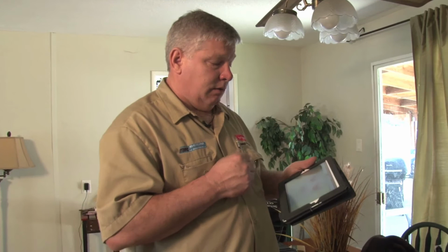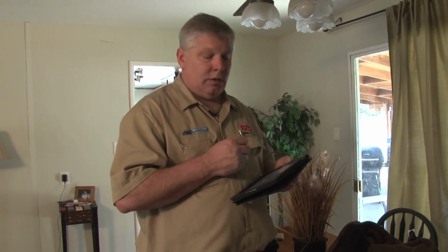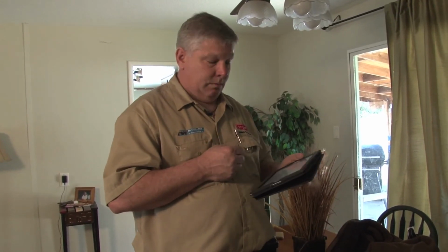And with that, we're going to say a 3.5 ton cooling system is required. The heating is not going to be a problem. We have a package unit on the roof which has heating and cooling built into it. All the 3.5 ton package units are going to have adequate heating for this house. So we're also going to look at staging heating and cooling. We'll have high-low heating so we're not overheating or overcooling the home.